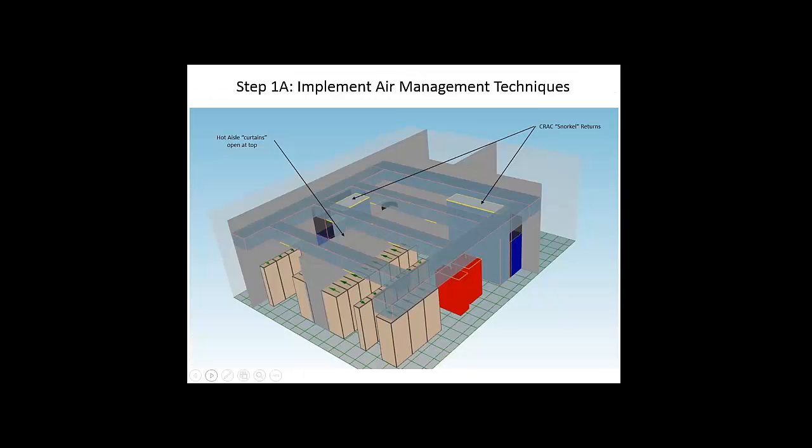So we've got the RTI in place. The question then became, what else can we do to improve it so we can drive up supply temperature just a little bit? One thing we could point out, Paul, is that if you compare those metrics with the original case, we have improved everything significantly just by pulling back on the airflow. Right. So there's a really big change here, much better already. Yes. But of course, you're going to show that you can fine-tune this now. You can go a little further.